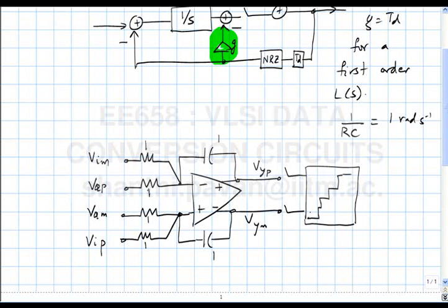Please note that we'll come back to this when I discuss a couple of minor details about the quantizer. But for example, in the 4-bit quantizer that you designed in your assignment, if you just took the comparator array, the output of the comparator array is nothing but what kind of code? It's a thermometer code, okay? And you can directly use that to go and, so what kind of DAC makes sense here?